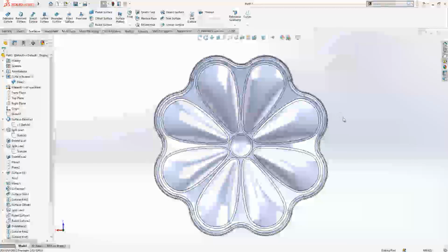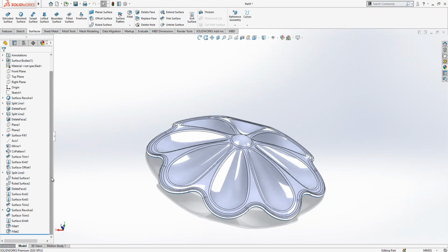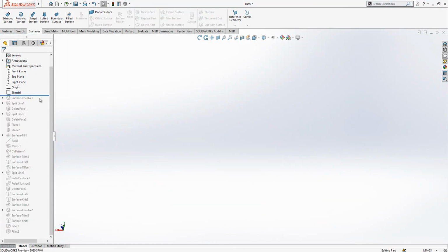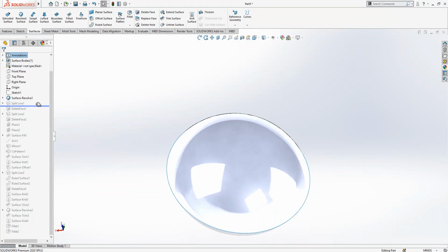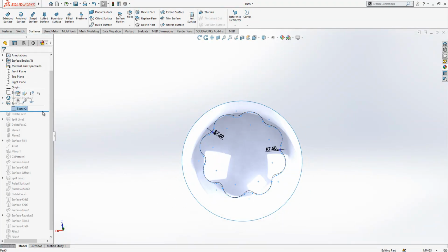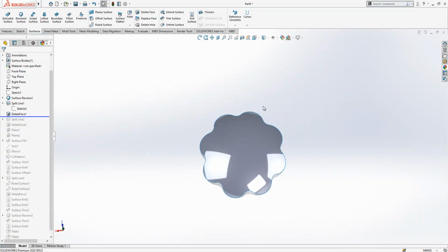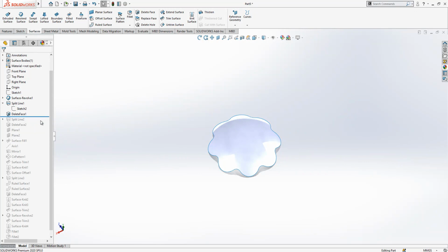Yeah, it's looking nice, and it's not that complicated, but there were a lot of steps. I hope you could follow my steps. If we look back at what we have done, first we create the sketch, and then we make a revolve, and then we made a copy of the first sketch. We only added there our radiuses, and then an operation for deleting the unnecessary area, and we made the first split.